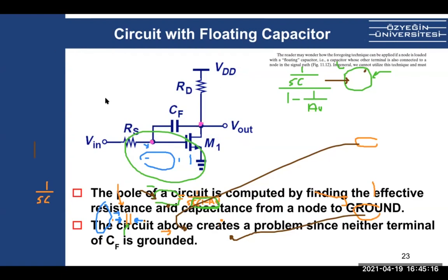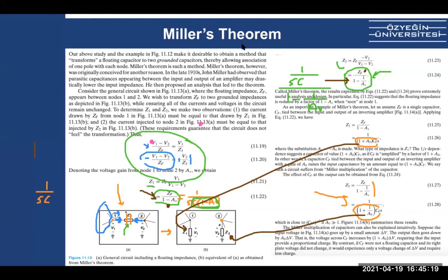So back to the circuit. So here, if we make the same logic, well, this will be V out and this will be V in. And the gain between them, AV, if it's like an amplifier as we saw, that means this will be big, this will go to 0. So we can summarize, if there is a gain between those, Z2 will be actually ZF. But Z1 will be ZF divided by minus AV, because A is big. Okay. So for that, the cap example.